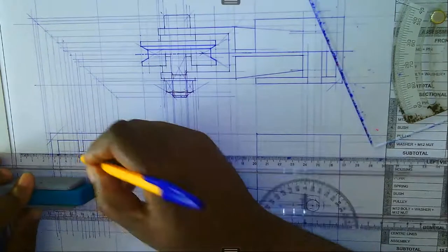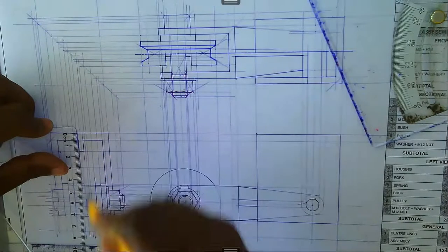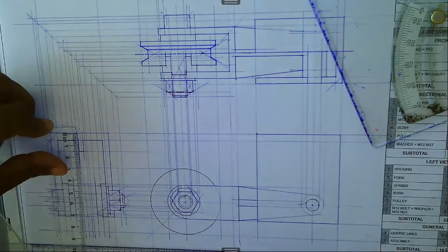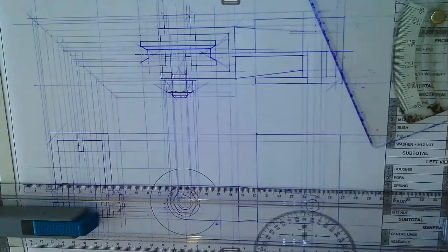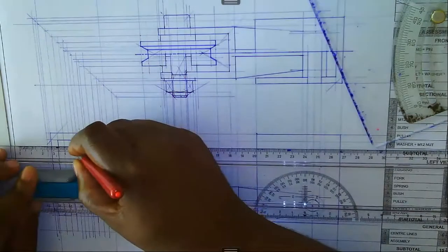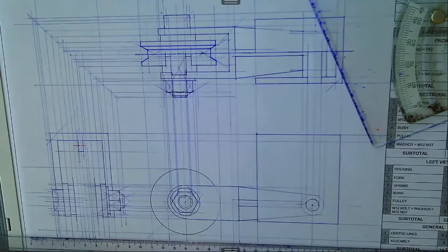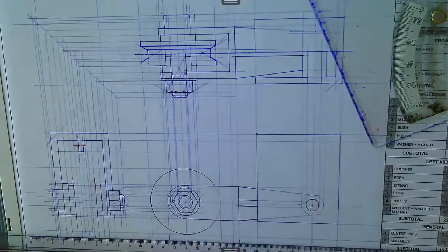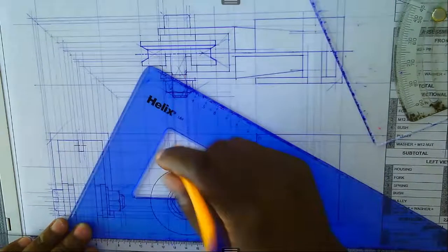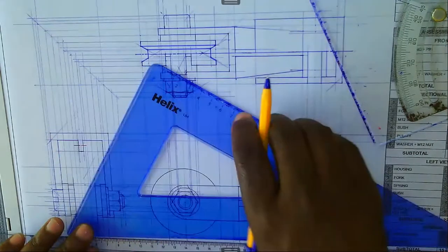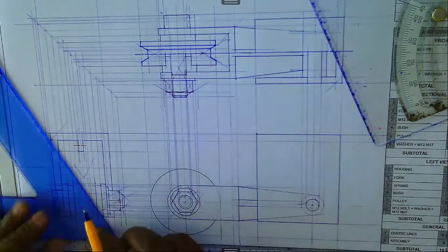Right, then also the bottom part, but still we need to measure from the top, that's our center. This shape. Yes, from the top, that's our center line, which is that. Right, I'm going to use a different color for the center lines. Yes. Okay, so we have got our specific center line there. We also now require the details with regards to the pulley. So we are going to have this one at 60 degrees and also do the same this side. Right, like that, at 60 degrees.